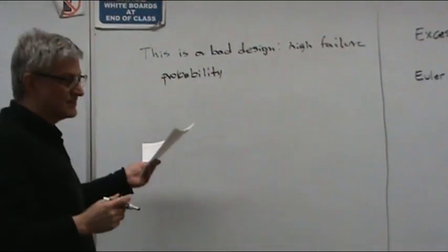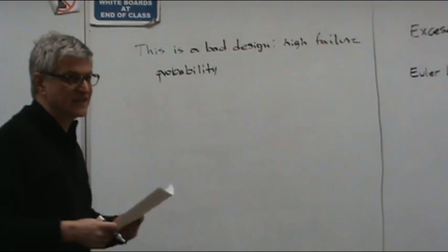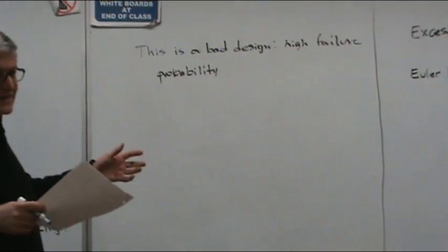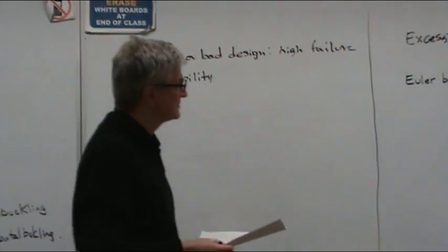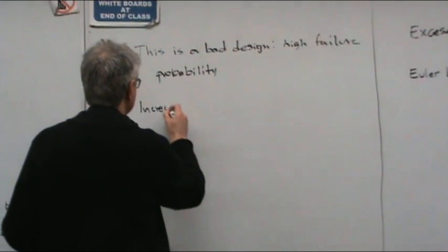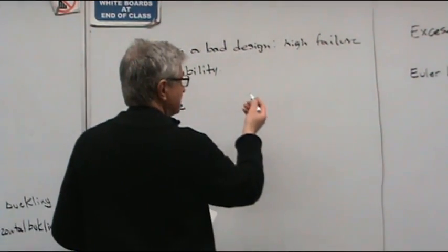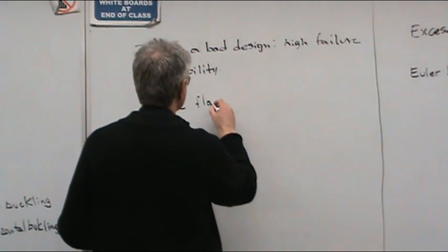Okay? And the other is that you got to do something with the flange. So either increase the thickness or make the flange longer. So increase flange dimensions.